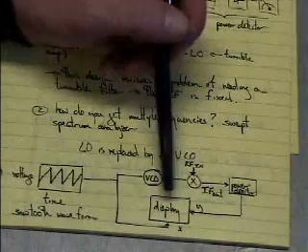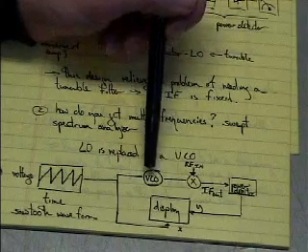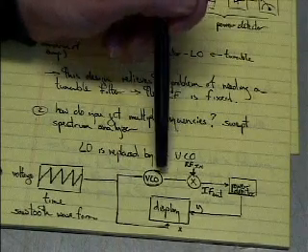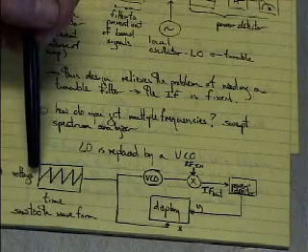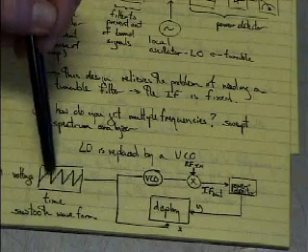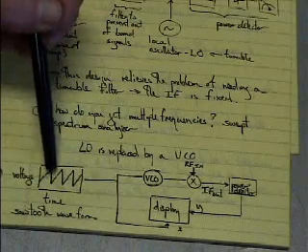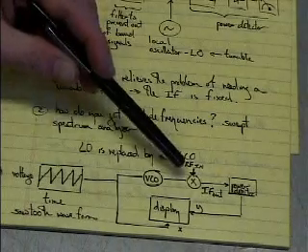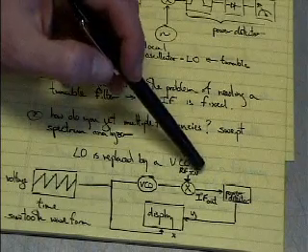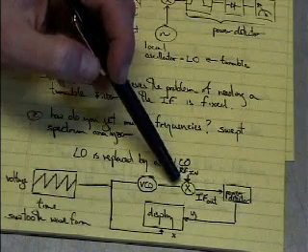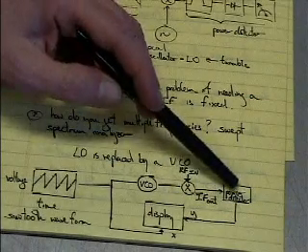And the way it works is we utilize, or what's utilized in the device is called a VCO, a voltage controlled oscillator. That is, its output frequency is dependent on what voltage you give it. And what's inside there is a sawtooth waveform generator. So it's basically putting out a sawtooth shape as a function of time, okay, voltage versus time. As this voltage ramps up, the output of this VCO ramps up, and you're going to look at a higher frequency here. Okay, so you're going to be tuning your VCO, mixing it with a higher frequency, and looking at a different frequency component in your power detector.